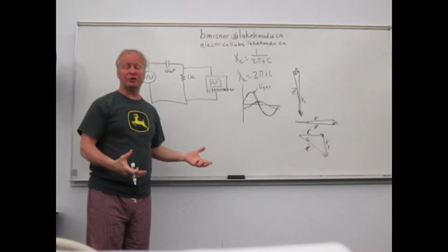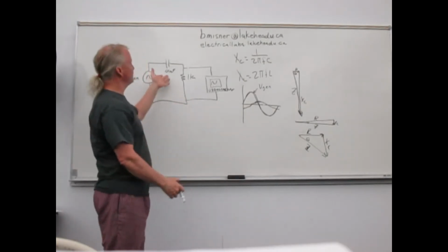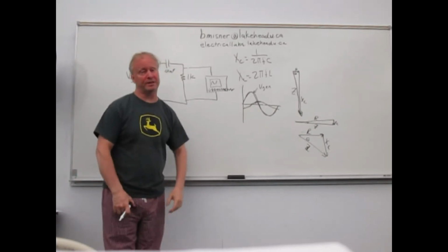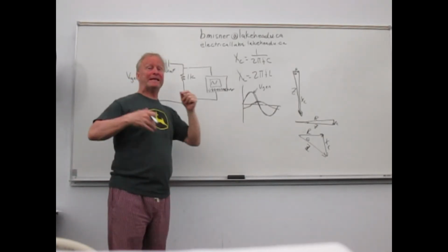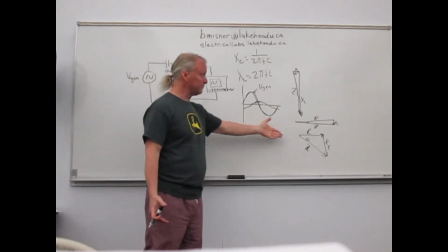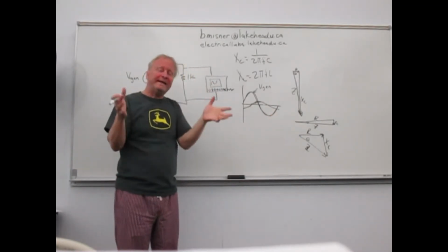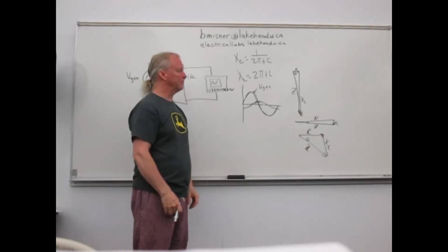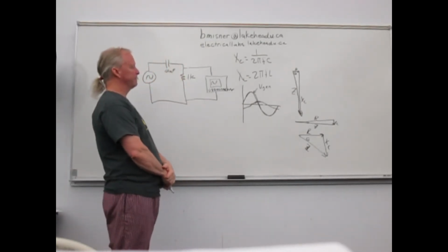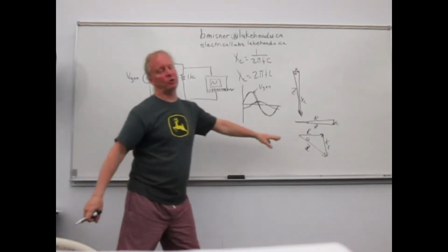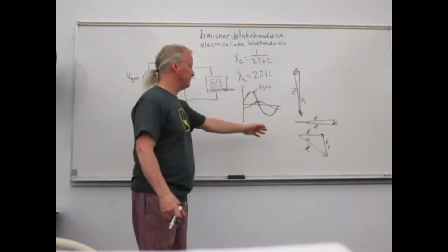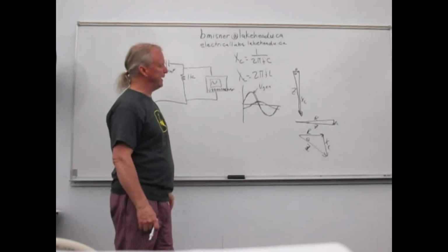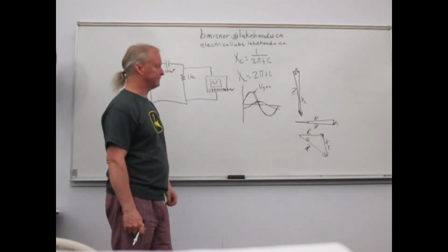So when I'm looking at the scope, like my first measurement, I really don't have to measure the phase shift because I'm going to see that it's almost 90 degrees. And then my very last measurement, I'm going to see that it's right in phase and that it's a 0 phase shift. Okay? But then again, all points in between, right? So again, now we can just use straight Pythagorean's theorem to go through and calculate these different things, right?